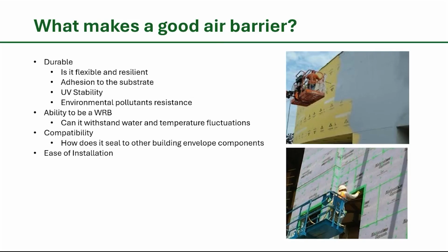Some have limited UV stability to 6 months, some infinite UV stability, some only a year. It's important to know that it affects the price point at which that material is brought to market. If you have long delays or anticipated delays, you want, in your cladding package, a more UV stable air barrier.